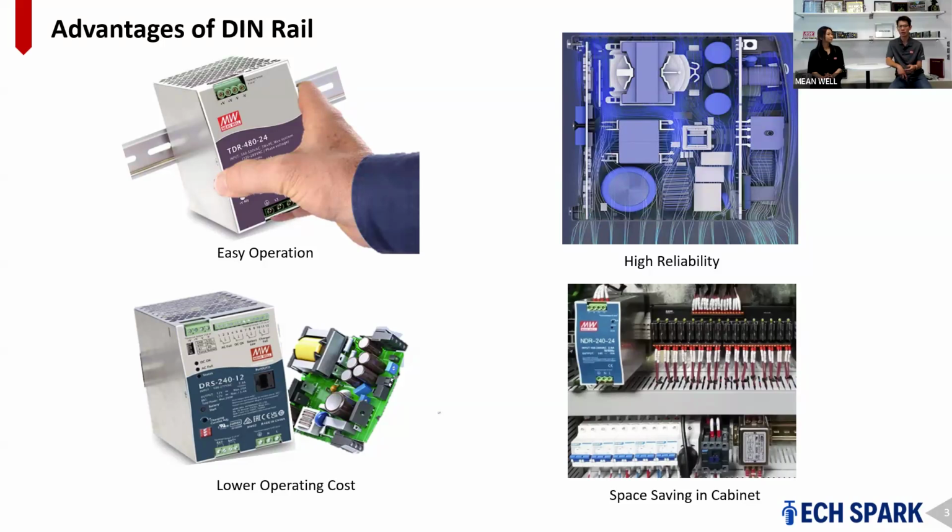We also talk about reliability. The DIN rail power supplies use convection cooling. This means that the electronics are cooled by only a natural airflow, which has a positive effect on the reliability of the power supply. The components that determine the lifetime, such as the electrolytic capacitors, are positioned at the coolest point in